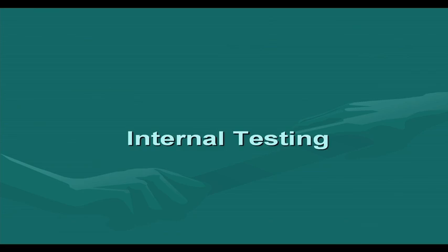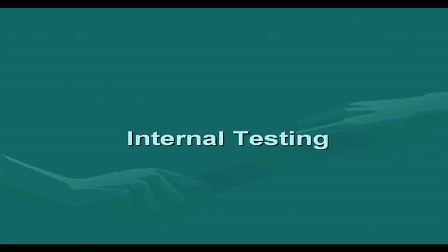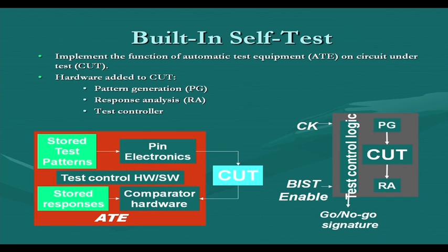With that idea, we will see how this test power consumption can be handled in internal testing techniques. Internal testing technique means mainly the BIST based approach. This is the basic built in self test approach. In BIST, what happens is that it implements the function of the automatic test equipment on the circuit under test.